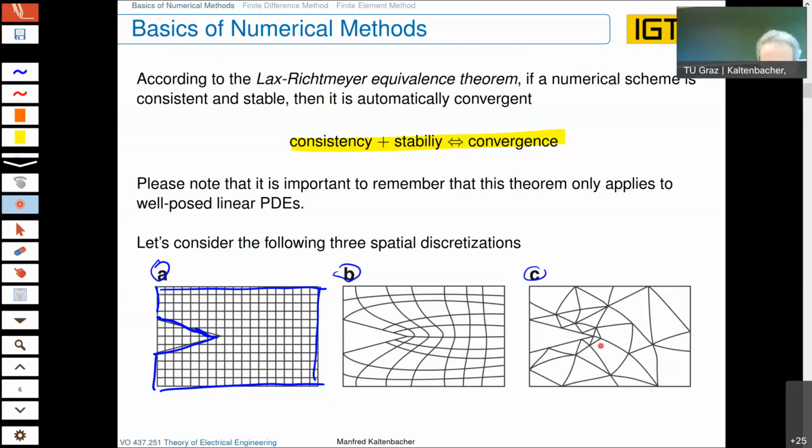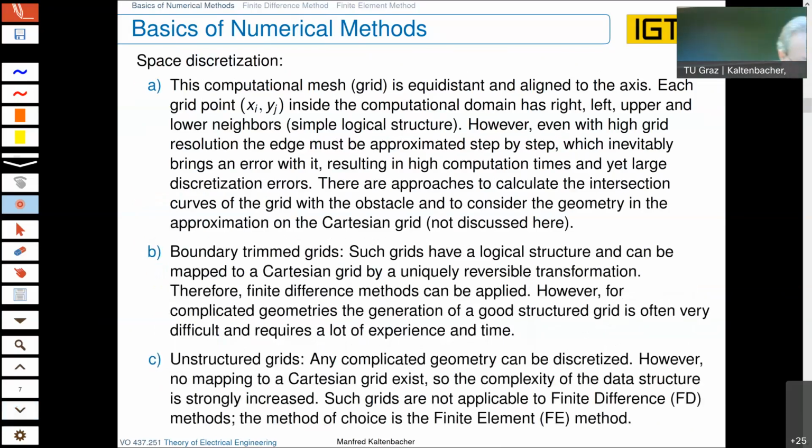And this, we will see, does not always give us the best properties, but we will never have any problem in subdividing any complex geometry into finite elements, because in 2D with triangles this will always be possible. In 3D with tetrahedra this will always be possible. Although these elements will not always have the best properties of quadrilaterals in 2D and hexahedra in 3D.